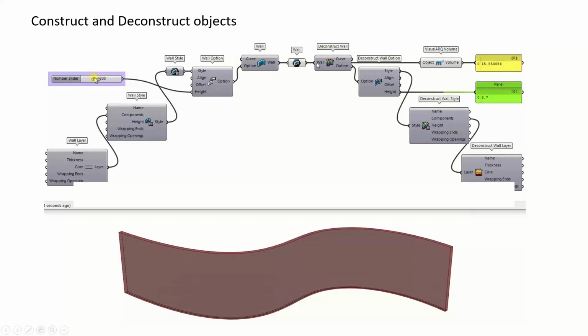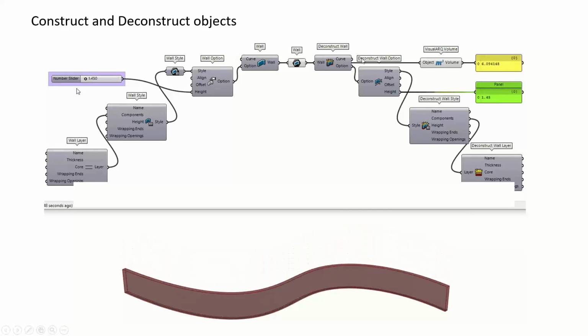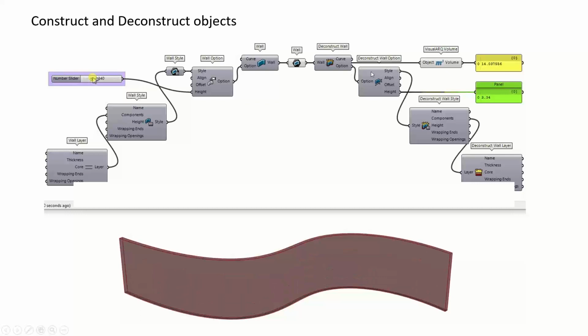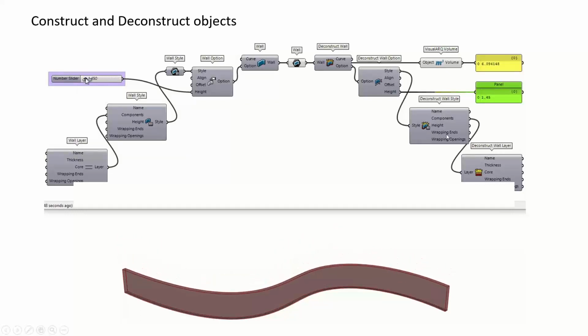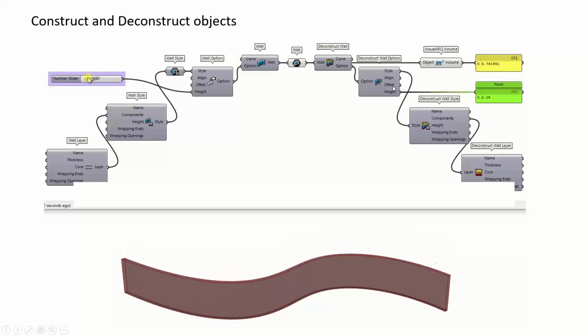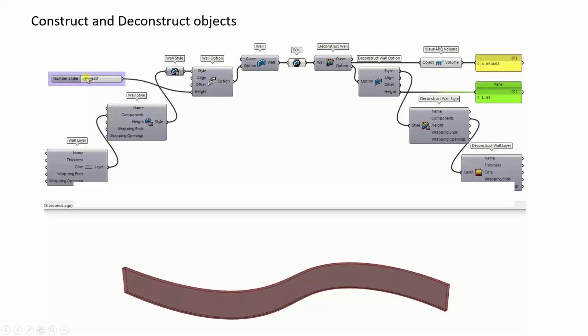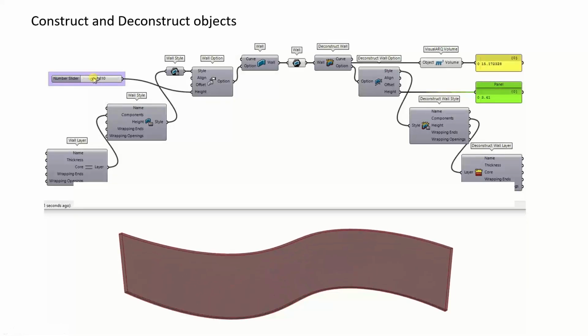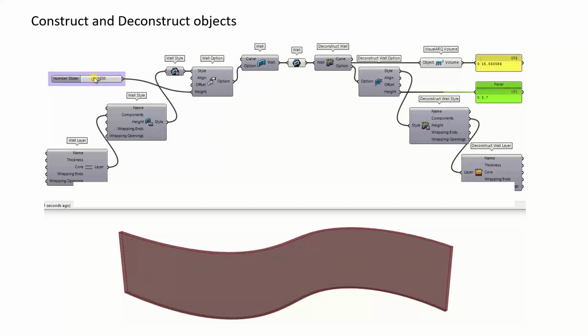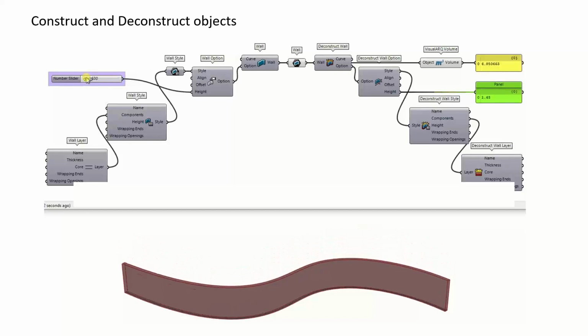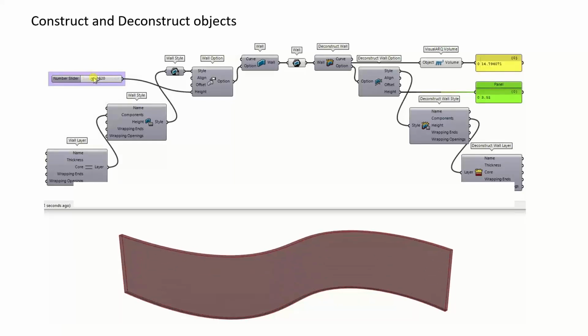So we can reference a wall and we can obtain its path curve. We can deconstruct its option to obtain the height, the information of the style, etc. Okay. Styles in VisualARQ are what define the object features. For example, in case of a wall, a style defines the number of layers a wall has, the thickness of each layer, the attributes, the material, and all these details.